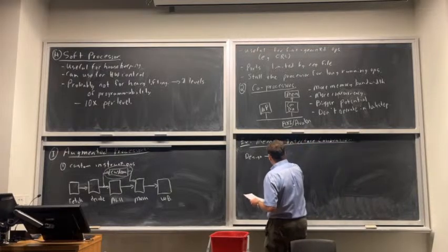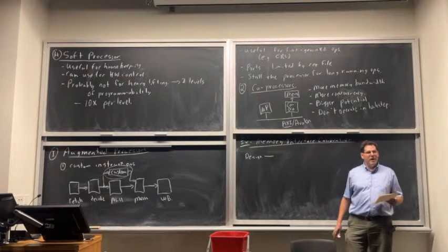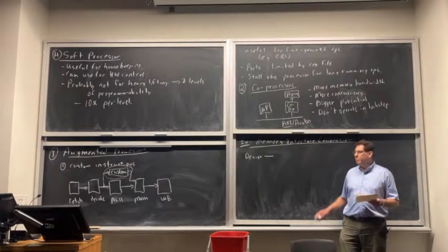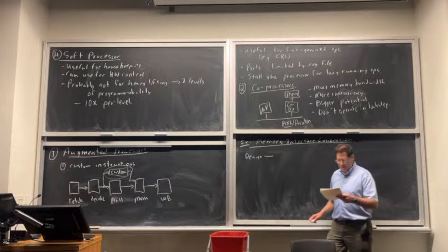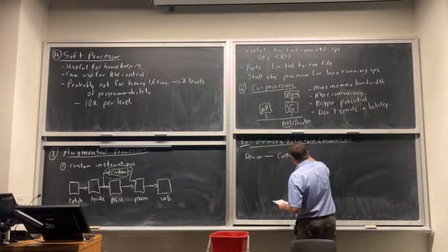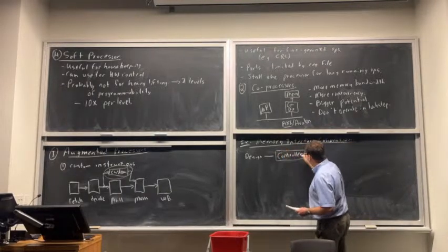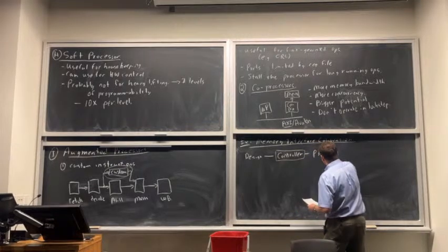You don't want to go write all the low-level HDL to talk to that memory interface. You just want to instantiate an IP core. And that IP core that you instantiate to talk to this off-chip memory has 2 pieces in it, something called the controller and something called the PHY.